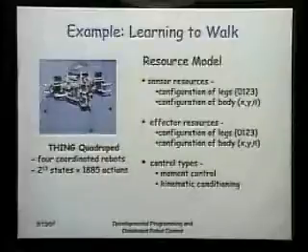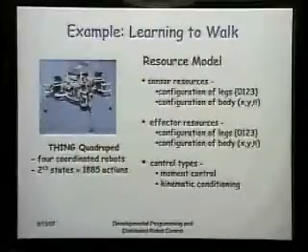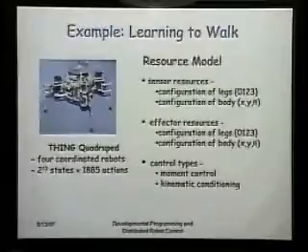If you're familiar with bipedal humanoids, most of them use zero moment point controllers, where they try to build a quasi-static polygon in the supporting structures of the feet. If the center of mass of the robot falls into the interior of that polygon, then the robot will stand there of its own accord. Right? Not dynamically stable, but it won't fall over. And if you lean forward and the center of mass goes out of that polygon, then you're unstable.